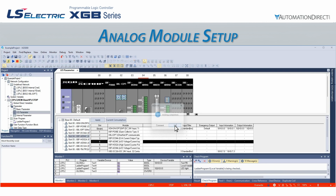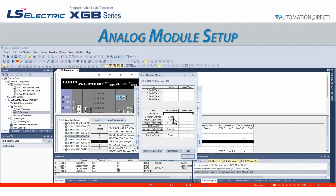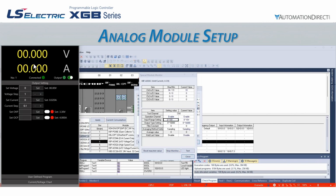Once we have written the updated configuration, we can then view real-time data for this input module. If we are online with the CPU, we can go to Monitor, Special Module Monitoring. This brings up a list of all special modules installed into our PLC rack. To select the analog input module in slot 4, we can either double-click on it or select it and then click Monitor. This brings up the Special Module Monitor pop-up window. If we click on Start Monitor, it will show us real-time data from the module. I have hooked up a variable power supply to channel 0 to simulate a 0 to 10 volt analog device. As I vary the voltage, we can see the counts changing in the software.